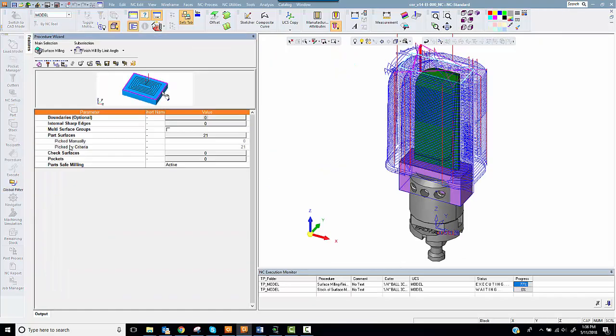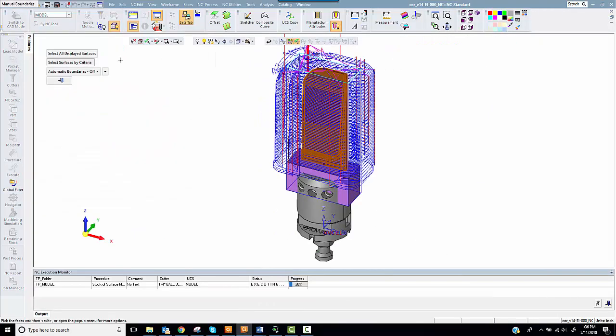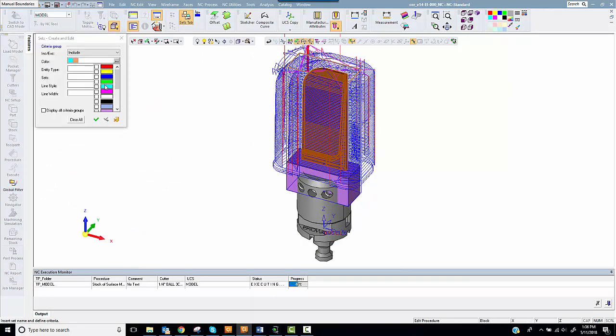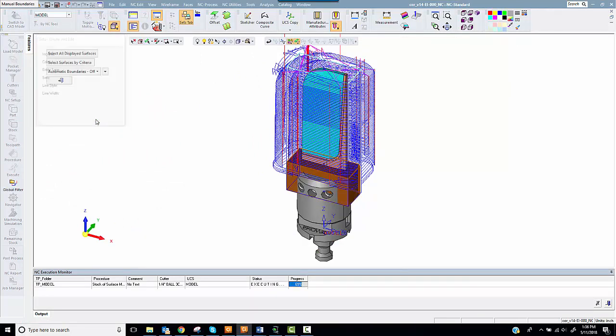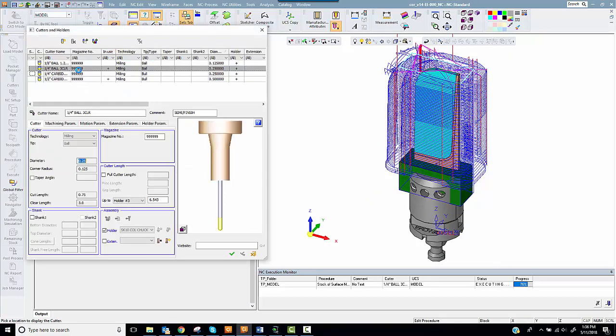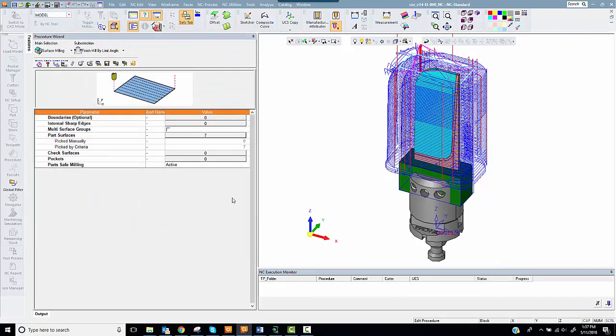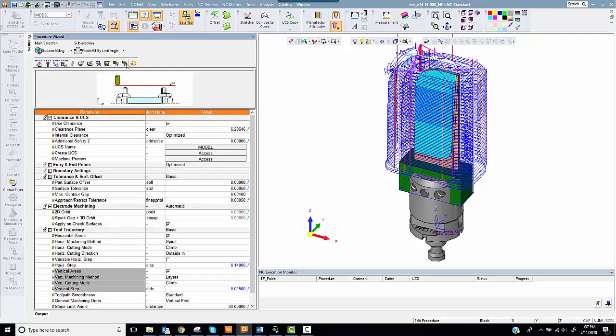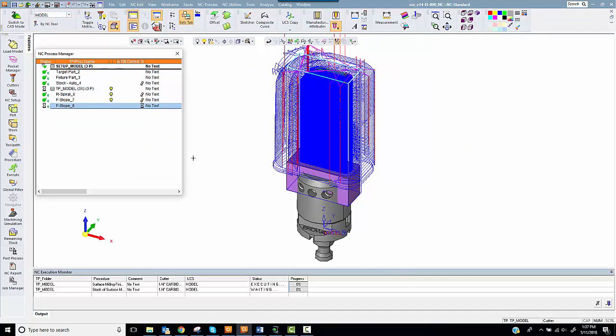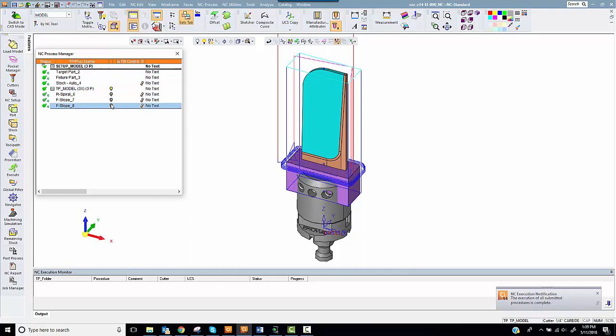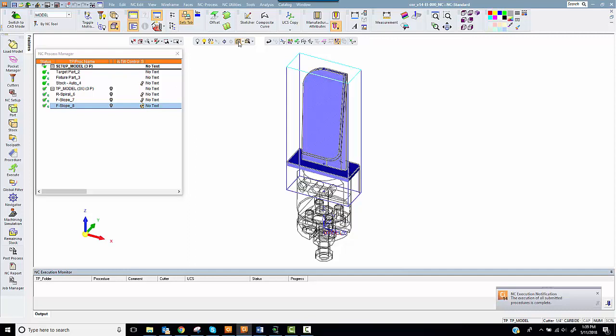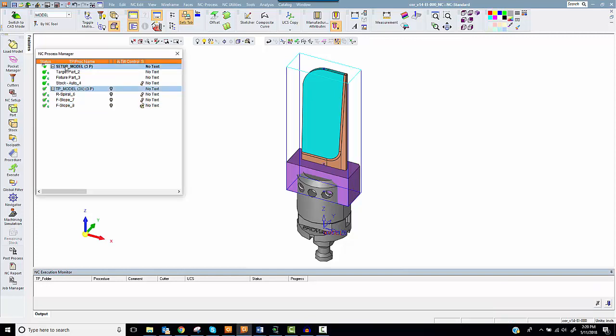Create another finish mill by limit angle, with the electrode base as the part faces. Grab a long 1/4 inch bullnose tool and calculate. At a glance, you'll notice the tool path stopped at the bottom of the stock for the finish mill procedure also. So far all I've done is create a tool path for a simple electrode in a very slow, tedious manner. I'll save the process as a template and close the file.